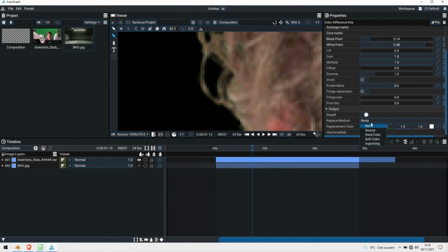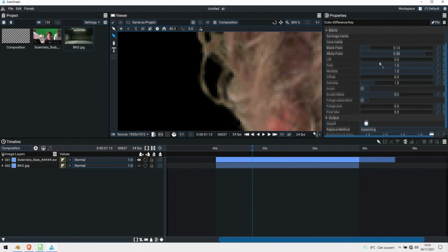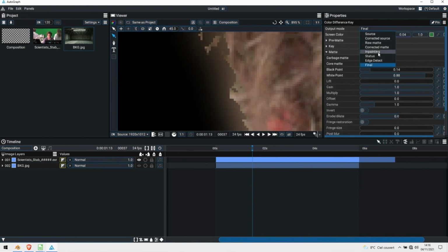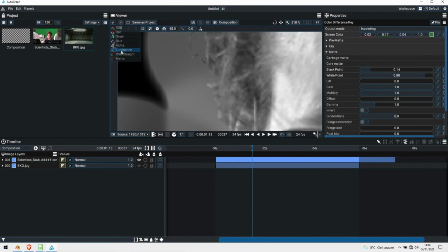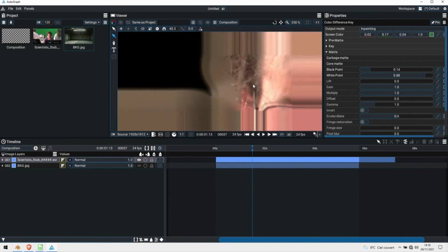Okay, when you want to remove this green part, you have to subtract green information. But in this case, we are not going to subtract. We are going to create another image which retains only the fully opaque pixels and extend. I'm going to show you, and extend the pixels around like this.